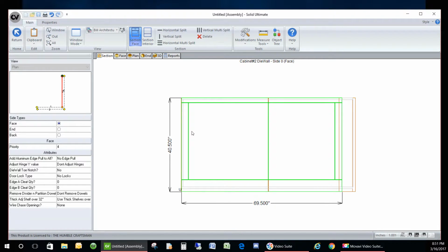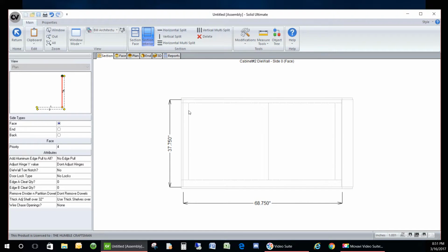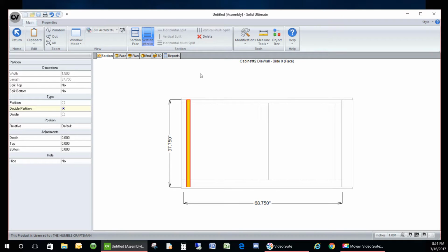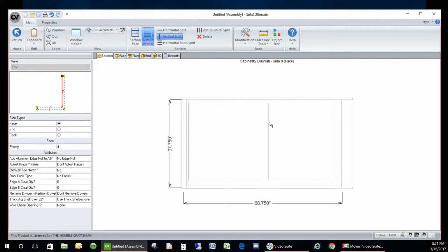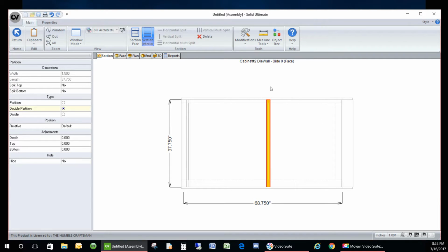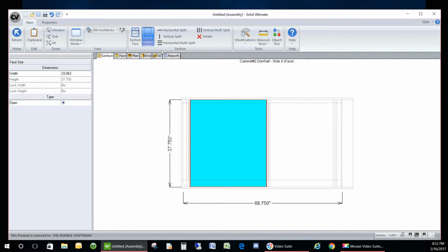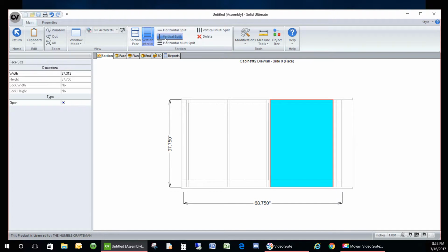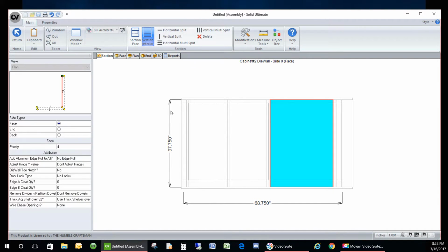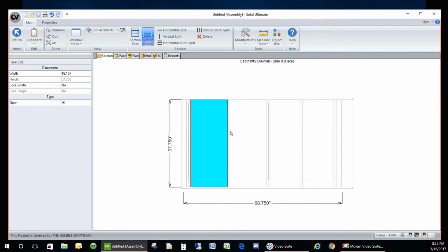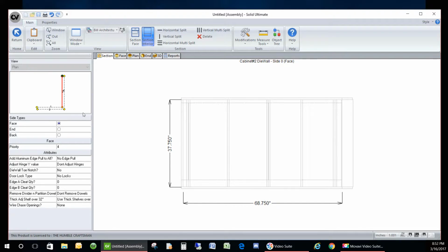So we'll go from the inside here. Go into the section view, we can see our reveals, and click off the cabinet, vertical split, double, click off the cabinet, vertical split, double, and we're going to go ahead and do this till we get all of them filled up. We have a 33-inch space. So I'm going to use this function to center. So here I'm clicking on the opening, then hitting the vertical split command. That way it will center the 2 panels respectively between the other ones.